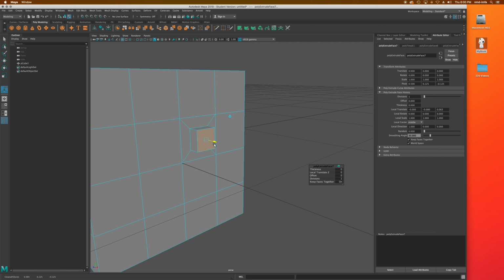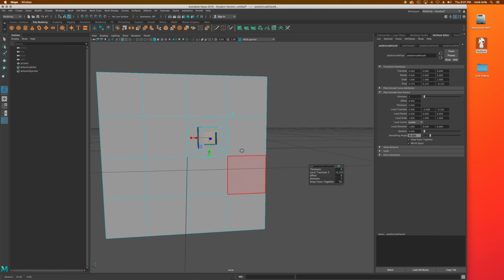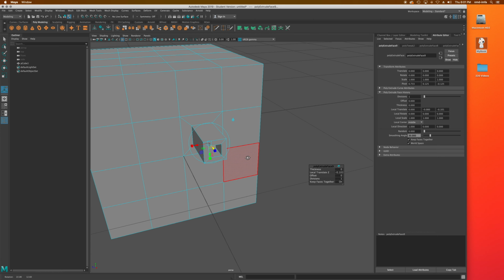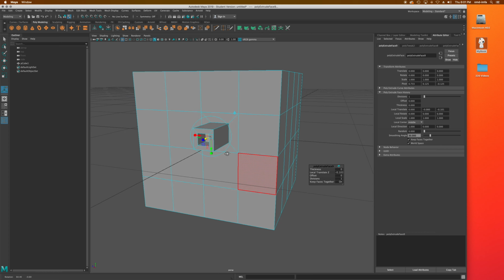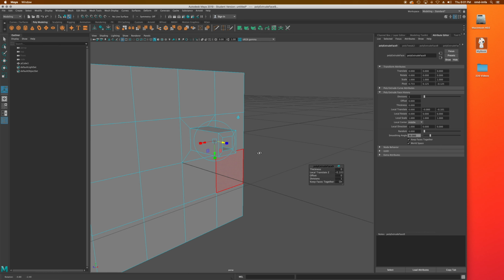So it's a really nice way to kind of add extra faces, do some subdivision going on, and then again be able to play around and make some really complex models all from one simple primitive, right? So Command E again and pulling that inward. So remember that combination of moving between the move translation tool or the scale tool along with your extrudes. Really powerful combination there. Okay.